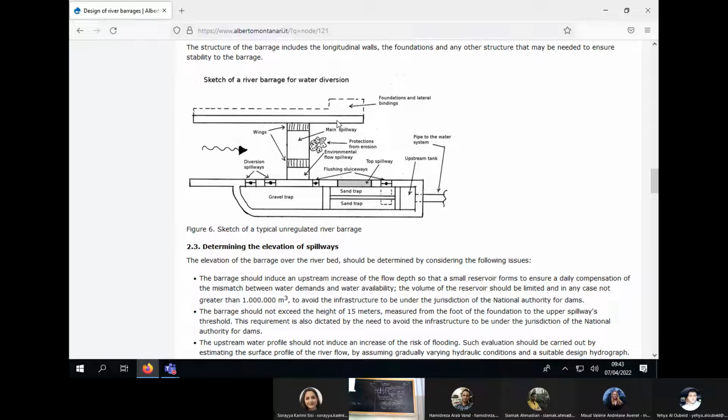The important thing is that you put gates here, and the reason for putting gates is not only not to exceed the withdrawal beyond what we are planning. There is another reason, which I already mentioned to you. It's not convenient to withdraw water during floods because there is a lot of turbidity. So during floods, usually the withdrawal is interrupted. Okay, very good.